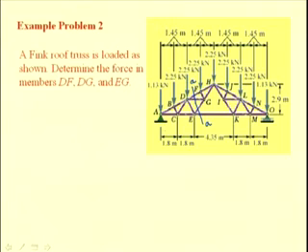If we consider this portion of the truss, we see that we have 4 unknowns, that is the force in the member DF, the force in the member DG, the force in the member EG and the force in the member EK. We know that in 2 dimensions, from the equilibrium equations of a rigid body, it is not possible to determine more than 3 unknowns.